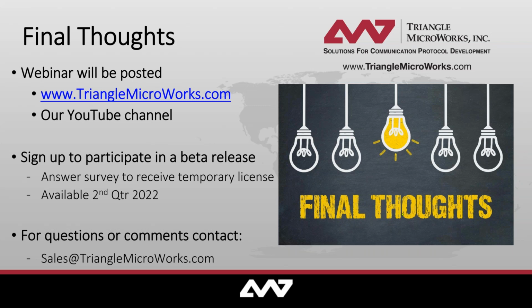These 3 parameters will be a little different depending on which protocol and how you're using it. But the first parameter would typically be a device name. So again, if your substation has unique device names, that works great. The first parameter could also be a DTM path, which admittedly no one's going to have in their predefined spreadsheets, but is fairly easy to generate if you need to. That would allow you to work with scenarios where you don't have unique device names in your substation. So we'll find the appropriate device.